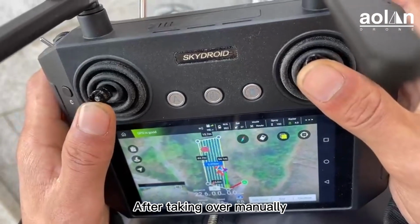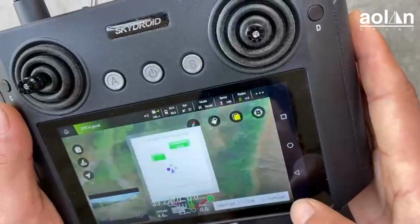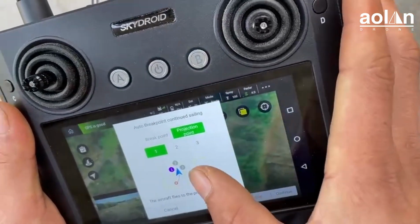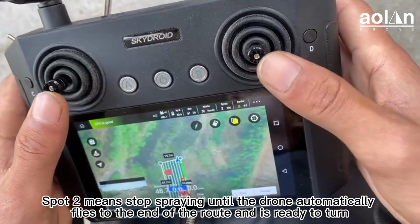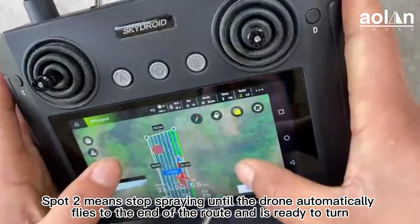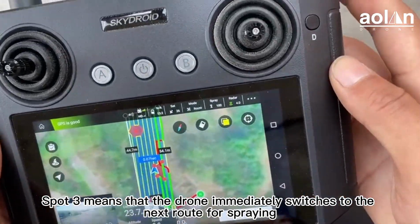After taking over manually, click the Continue button in the lower right corner to go back to autonomous flight. Choose from 3 options for breakpoints. Spot 1 means to continue spraying from the breakpoint. Spot 2 means stop spraying until the drone automatically flies to the end of the route and is ready to turn. Spot 3 means that the drone immediately switches to the next route for spraying.